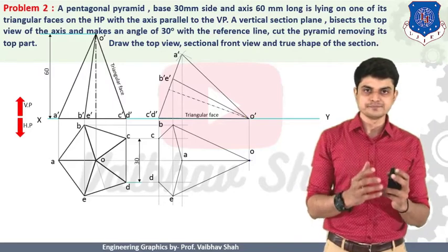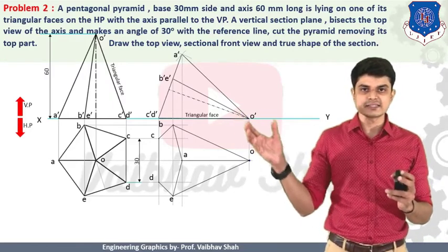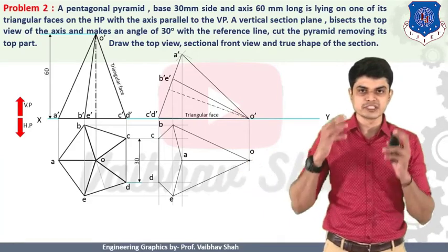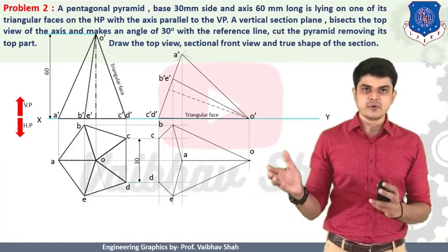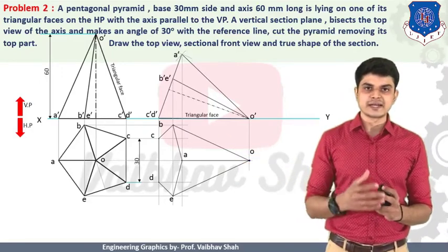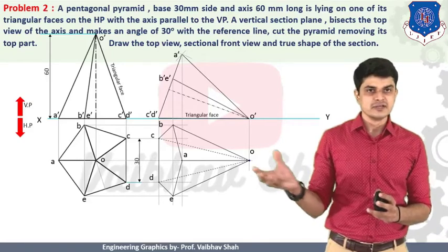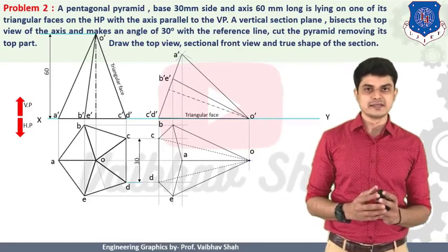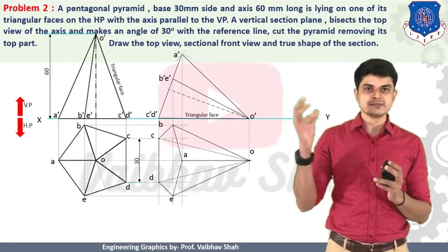So that means the lines connecting O dash C dash and O dash D dash in the next view, that means the top view, must be hidden lines or dotted lines. So let us put these lines OC and OD as dotted lines because they can't be visible by taking its top view from this top direction. So we have drawn these two lines as hidden lines. Right? Very easy. Now we have drawn our object by shade position.